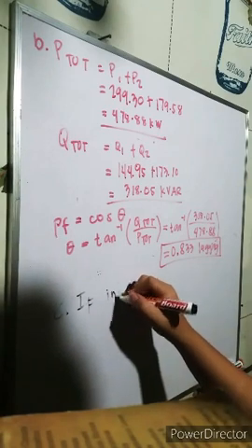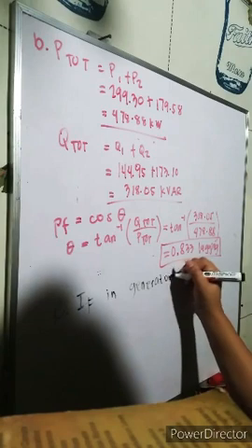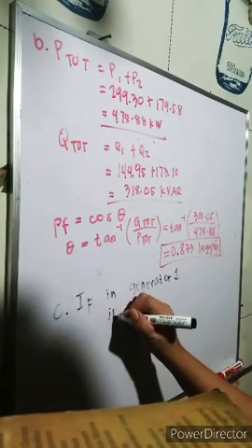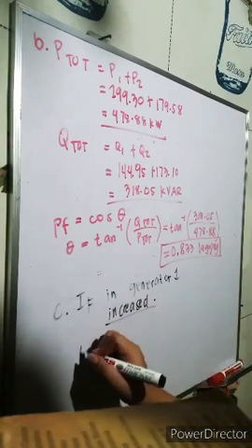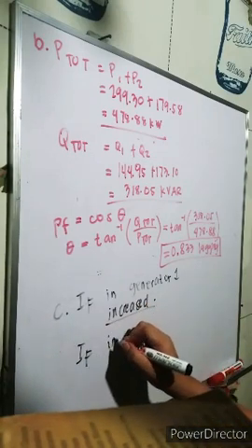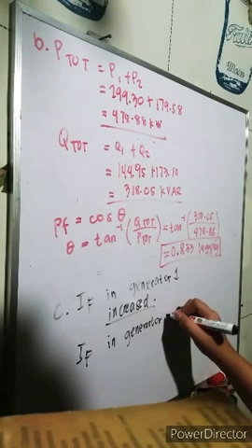So in C, what must be the direction of the field current? The field current in generator 1 should increase, and the field current in generator 2 should simultaneously decrease.